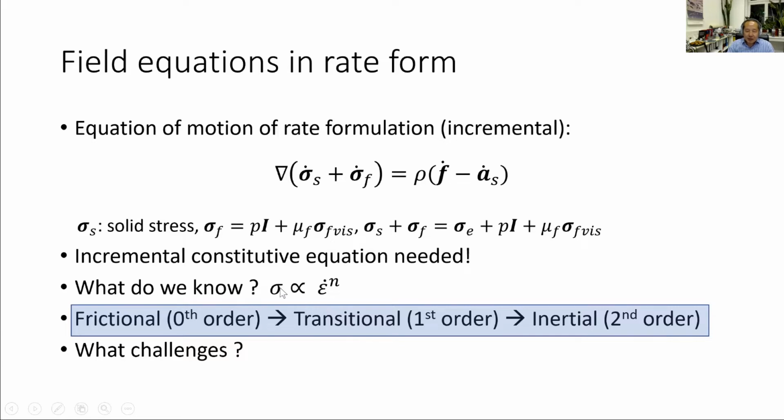You know, the debris flow community will probably use tau and gamma dot, but later you will see that it's better to use the stress tensor. So you put this kind of stress tensor in relationship to the strain rate. And we may have a zeroth order, and the first order, and towards the second order. What do I mean? I mean the frictional.